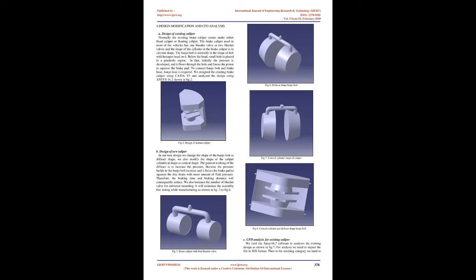2. Materials and methodology. The material of a brake caliper body must be rigid to allow less deflection, and should be light to reduce the final weight of the assembly. However, the most important property considered for selection of the material is the modulus of elasticity, as, for a caliper, stiffness is more important than strength. Most of the commercial vehicles use brake calipers made of cast iron because of low cost, high modulus of elasticity, 210 GPa, and good machinability.